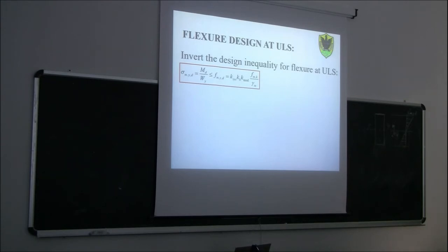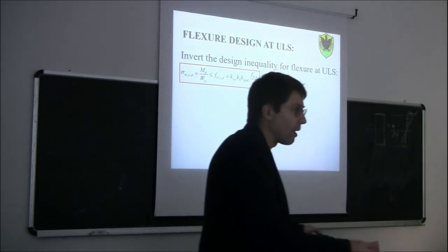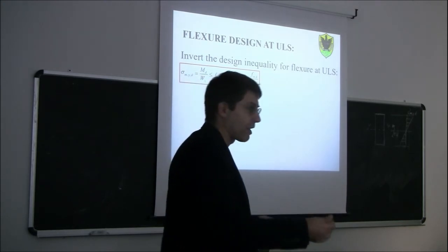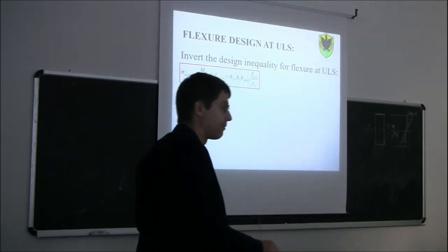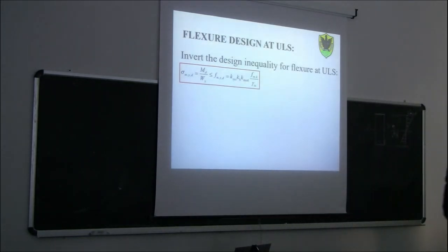Or you could say, okay, usually, for example, the GL28H is one of the most used strength classes for glulam. So you use GL28H. Okay, you make an assumption at this point. Gamma M, do you have gamma M? Partial safety coefficient? Yes. Because this is given by the regulation, either the Eurocode or the Italian code. So in the end, you see, the only unknown is Wy.